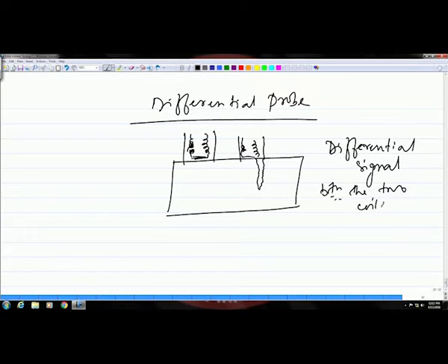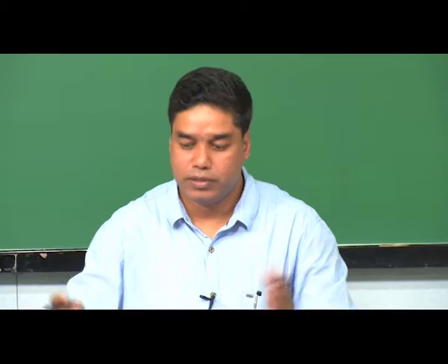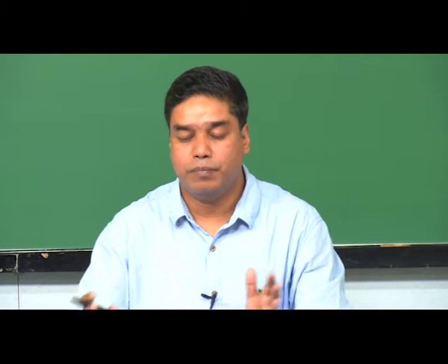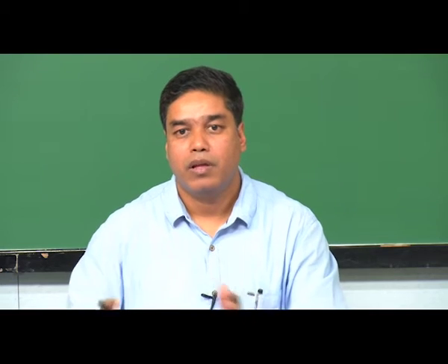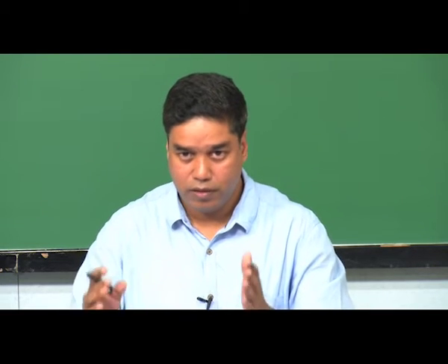And this will be sensed by the sensors that you have in the system, and the crack signal will be shown on the display. Okay. So, this is based upon a differential signal between the coils when one of the coils will be over the defect.